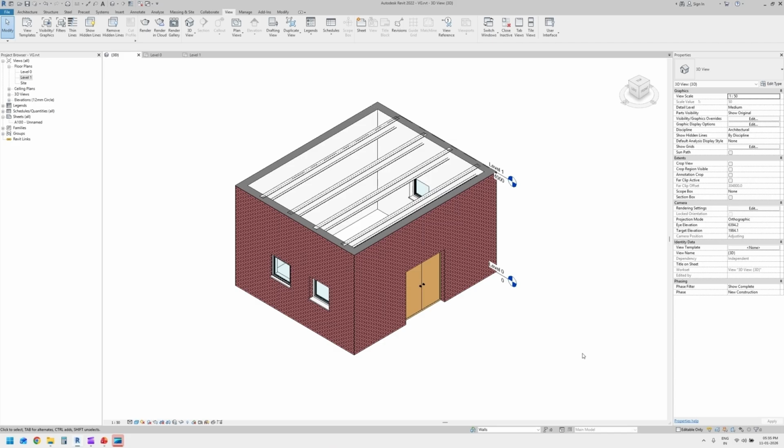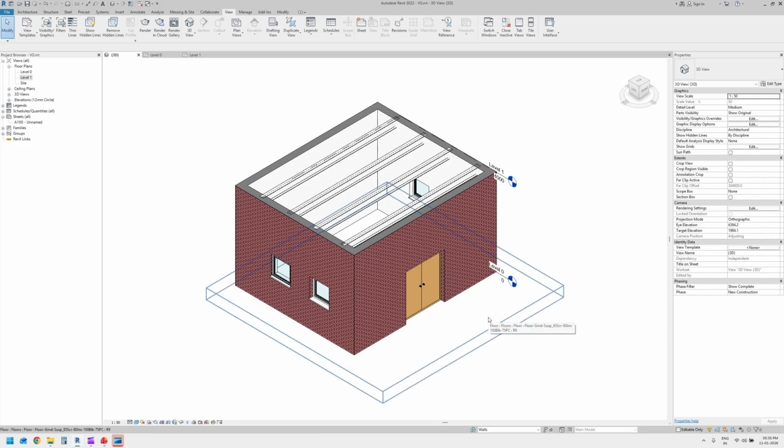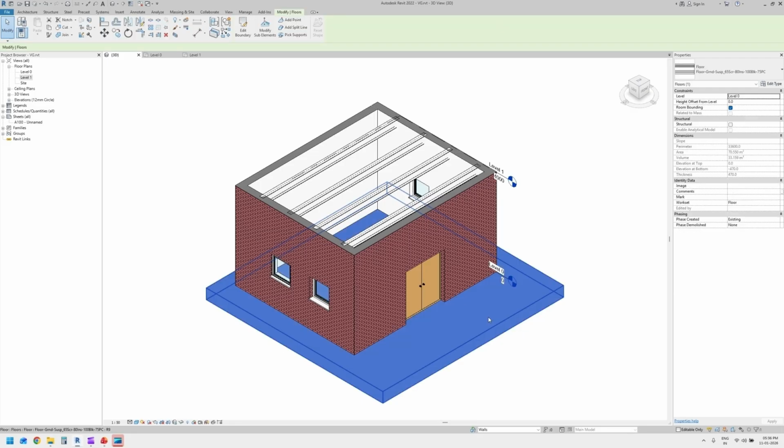In some instances, you will find that your element is not visible and you have checked a lot of possibilities, but when you move your cursor around, you can find that element. In these scenarios, pick that element and check whether it has any filter overrides which are making the element invisible. It could be white color or transparency.